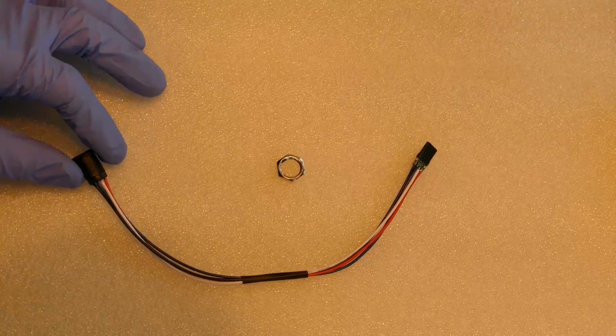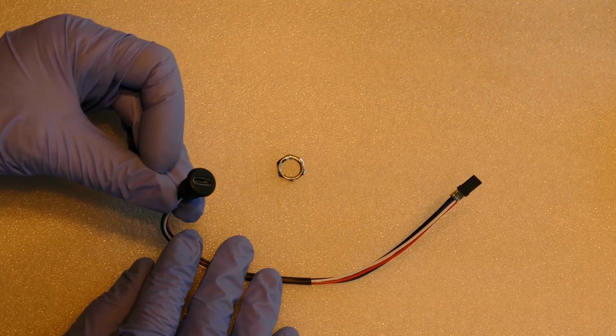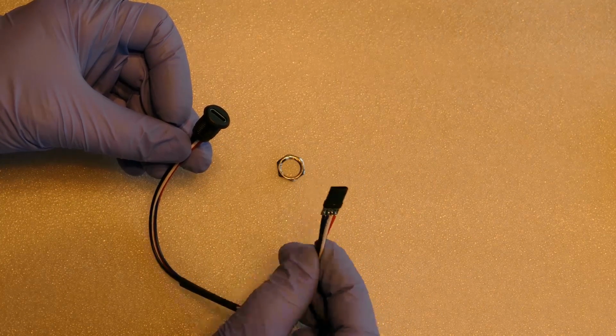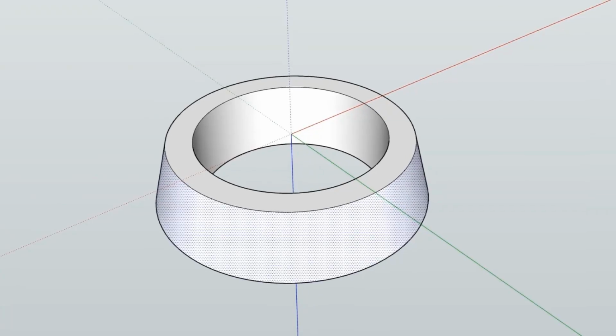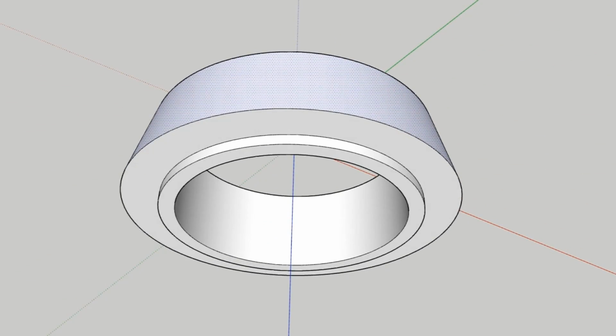I bought a 4-wire panel mount USB Type-C connector on AliExpress because it's the only one I could find that would fit in a 1/2-inch 12.7mm opening in the back of the enclosure. I designed and 3D printed a grommet to hold the USB jack snugly in the case hole.